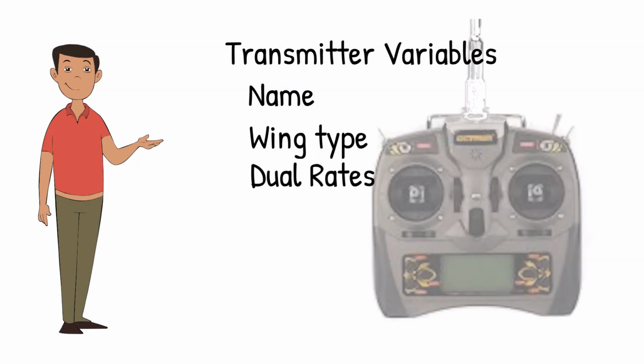Next, refer to the model's instructions and see if it recommends control stick expo or exponential stick movement. You'll normally set expo as a percent of total movement. For most brands, positive expo results in reduced control movement for stick movements near the center of the range. A little expo can smooth out the nervous inputs new pilots often experience. Expo doesn't limit total control throw, only the rate at which the controls get to its limit.